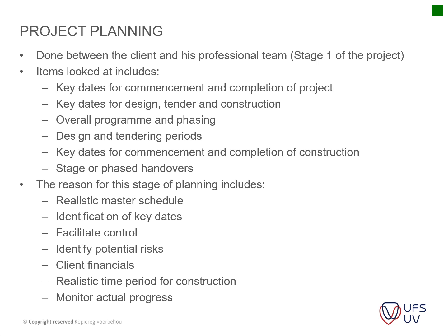Okay, then we get to project planning. This is done between the client and his professional team. Usually it starts at stage 1 of the project and continues further on. Items that are looked at are the key dates for commencement and completion of the project, key dates of design, tender and construction, overall program phasing, design and tendering periods, and stage or phased handovers. The reason for this stage planning includes we need to get to a realistic master program.